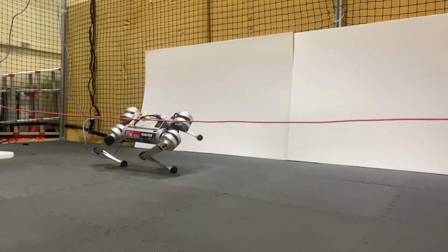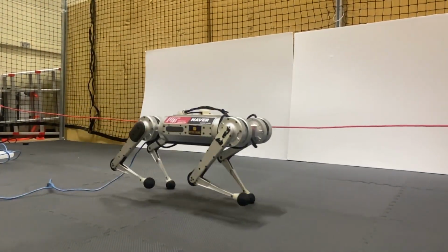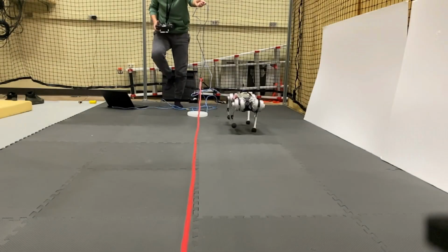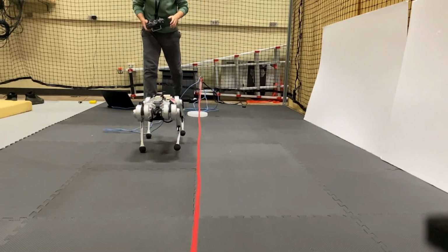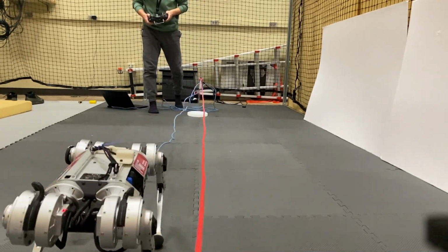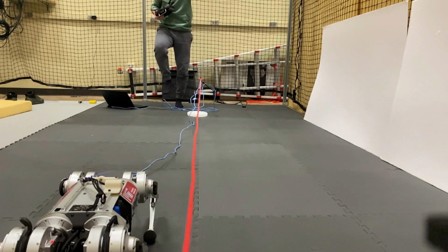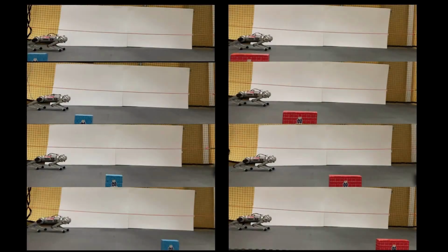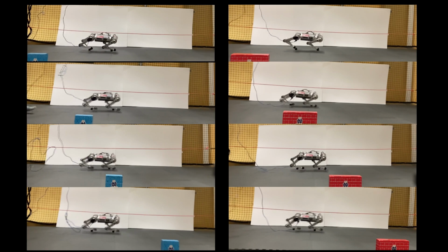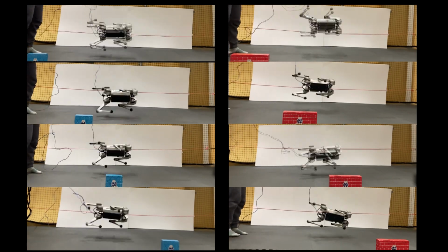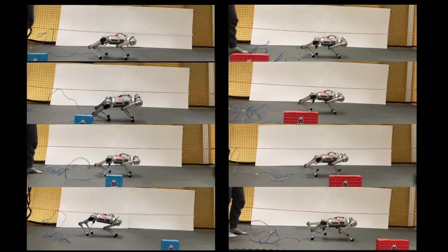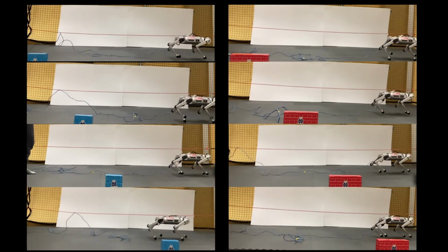We further commanded the robot to perform a running barrel roll without the intermediate stance phase before taking off. We emphasize again that the same in-place barrel roll reference is used here. We repeated this experiment 22 times to examine the reliability of the control framework and achieved a success rate of about 70%. Eight successful experiments are shown here.